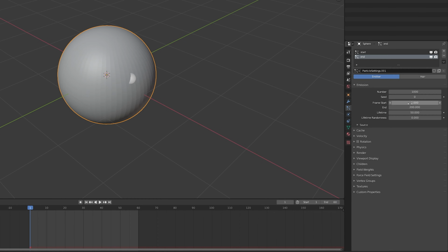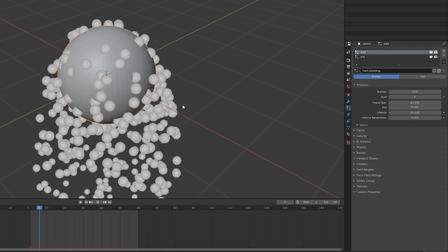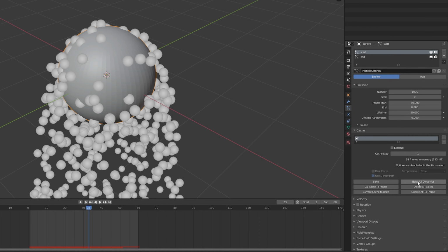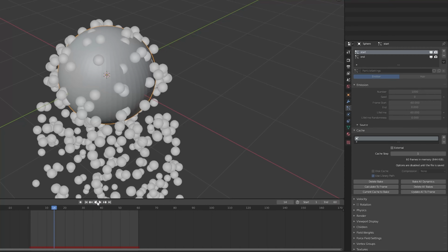Now I'm adjusting the segments so that they form a perfect loop of cyclical animations. So I'll set the segment's lifetime to equal the animation duration of 60 frames. For the animation's beginning, I set start on the -60 frame, and the end at 0 frame. Let's check and see the cyclical animation of segments. They're all flying off somewhere, but we need them to scatter in different directions.